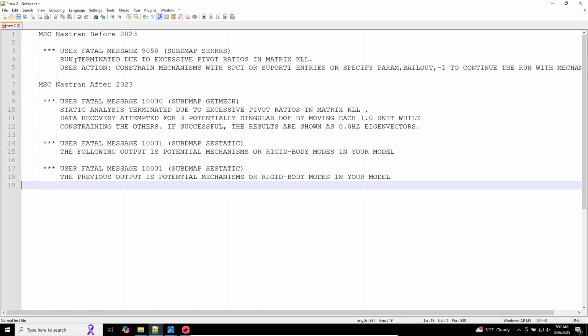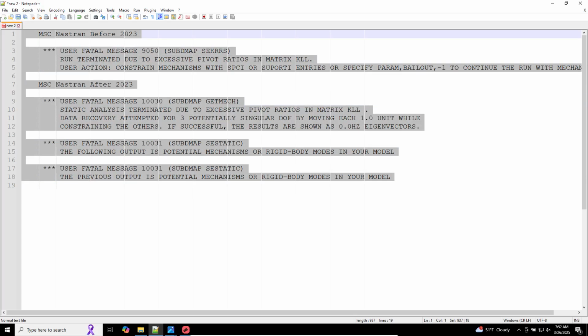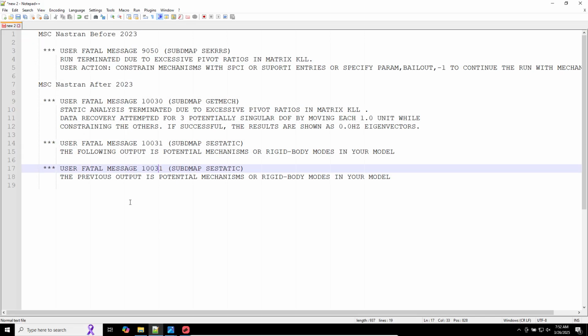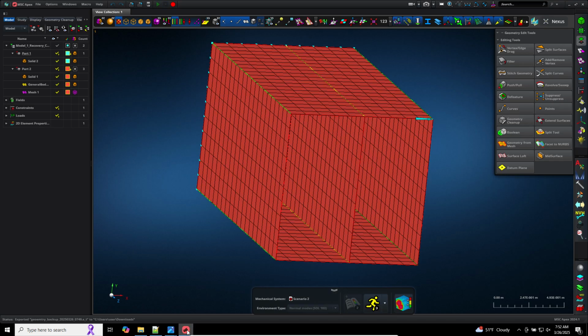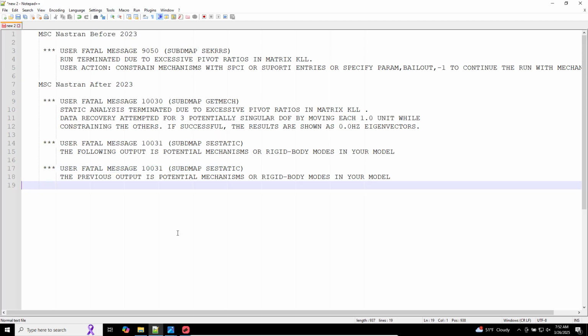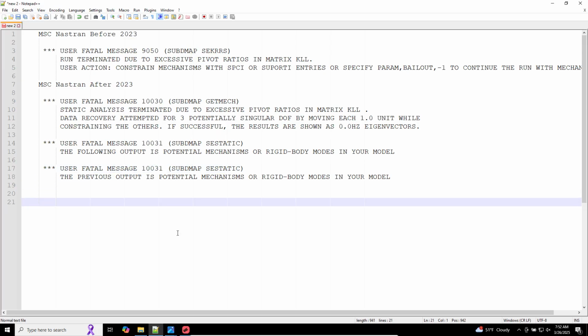The goal of this video was to discuss how to fix these UFMs 9050 and UFM 10030 and 10031. These are some of the most common errors you'll find when you're working with Nastran. This was just one possible error. Again, this error happens because of some of the forces. So I'll say sigma Fx.